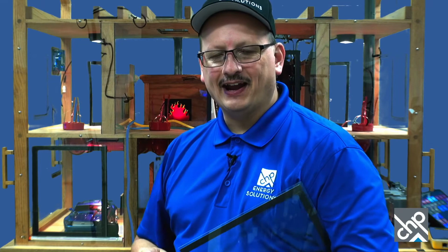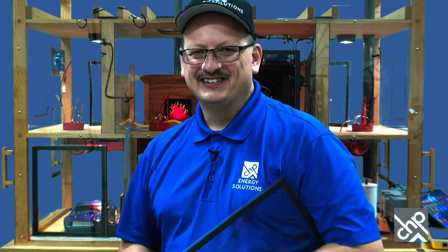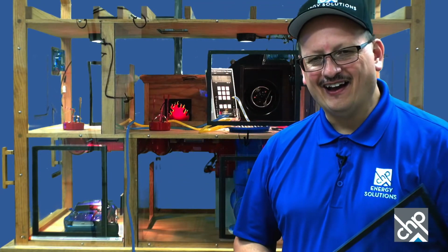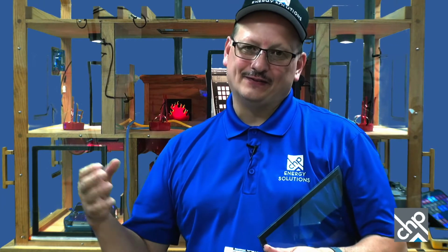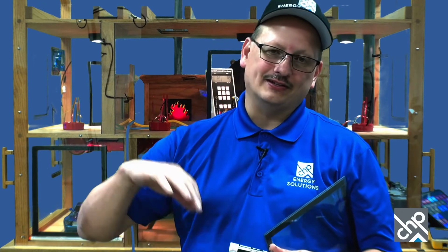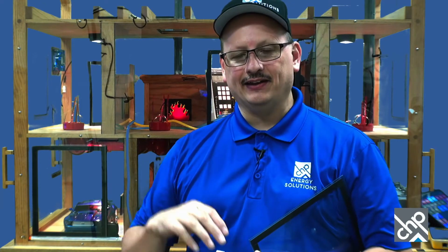I was talking about Thule in the Mad Air. He had this table with all the different ways to do it. I called it 50 ways to leave your louver. I know it's really bad. That's one of my favorite bad jokes. But basically, you have to have a louver or some way to get the air from one side of the bedroom back out into the hallway, if you're trying to relieve the pressure.